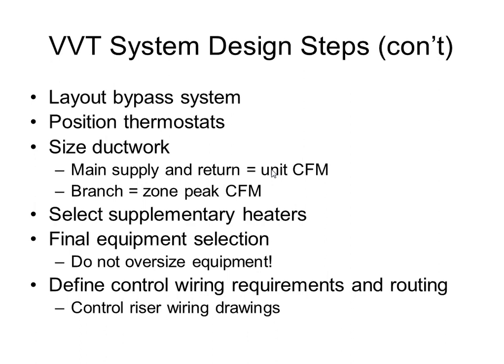So once you have your thermostat position set up, you want to size your ductwork. Your main supply and return duct, you need to size for the CFM of the unit, and then each of your branches downstream of the zone controllers will be sized for the CFM of each zone, the peak CFM. Supplementary heaters are not always used, but they are a nice feature to have if you have the budget for it, and you would want to look at where to implement these after you have your ductwork sized.